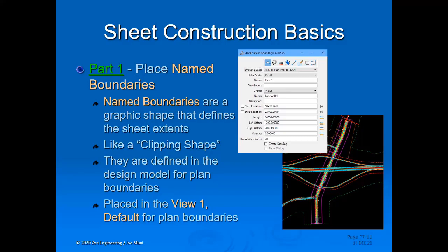Okay, so again, I will demo all of this out for you, but I just wanted to give you an idea of how it works. Now, not to put the cart before the horse, but there are some new settings. Whenever the plan model is placed in that view one default, there's a setting in the references when you create the drawing model called sync view.